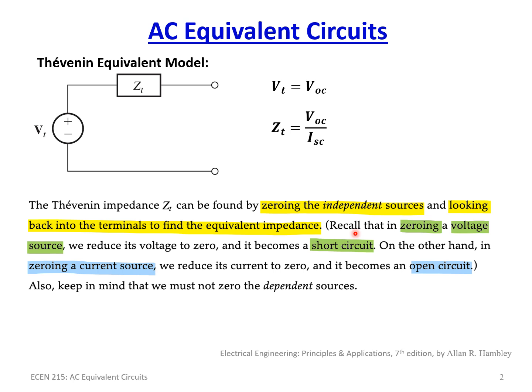So if you were really good at doing the resistance equivalent to get the Thevenin resistance, RTH, then this will work just as well using the same process. Again, when you zero independent sources, voltages become shorts and currents become an open. They just leave the circuit. And then you just end up with a circuit full of impedances.